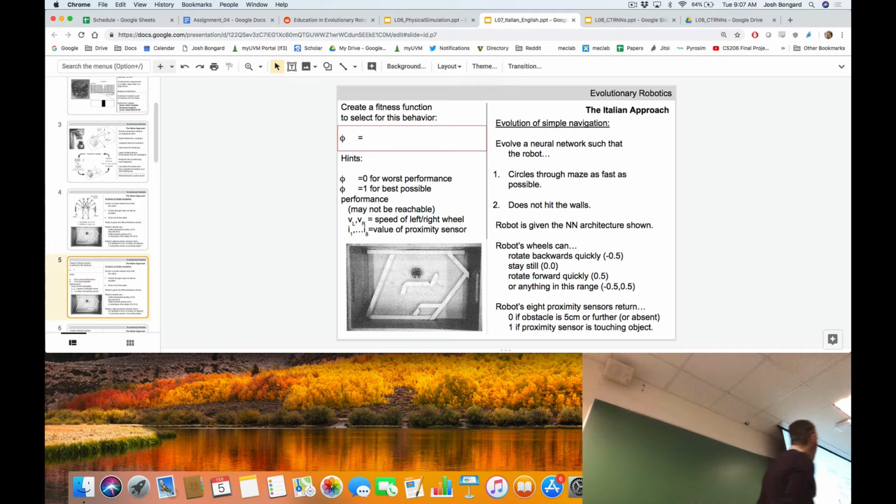Vehicle speed, okay, but we have speed of the left and the right wheel. We don't actually have vehicle speed. You can maybe compute it using VL and VR. How might we do that? How would you compute the fact that the robot is actually moving forward or back? You do it like with vectors. Okay. Vector for the right wheel, the left wheel, the length of the vectors, how fast that wheel is moving. Possibly. So we could create a vector for VL. We could look at VL at T0, T1, T2, and T3. Is that what you had in mind? Yeah. Okay, so we could do that.